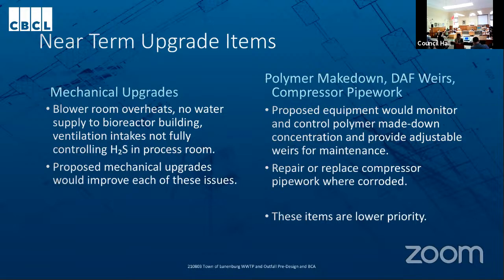Additional instrumentation would allow the polymer to be dosed accurately based on the inlet conditions of the wastewater. As seen from a DAL study, the main parameters are salinity as well as TSS. So we would propose to add TSS meters as well as conductivity meters to measure the salinity and TSS, along with dissolved oxygen meters within the equalization tank and the MBBR.